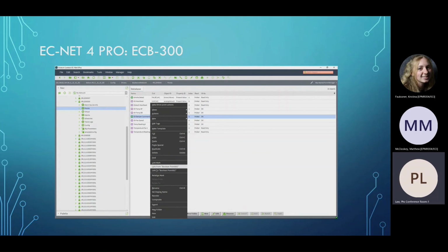So now what that does is it says, okay, in the modbus TCP driver, I'm now configured to be 601. Whatever's in modbus register 601, that's my value. And then this says, okay, well then if that's my value, that's your value too.